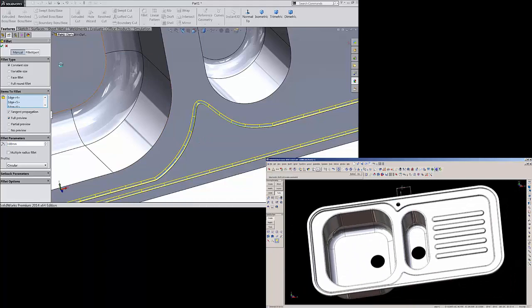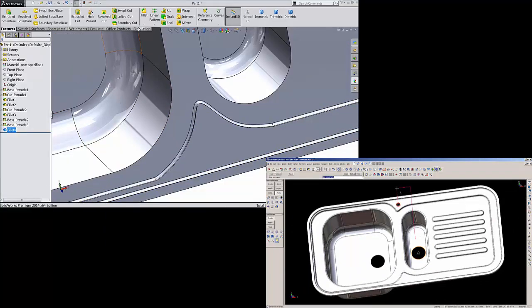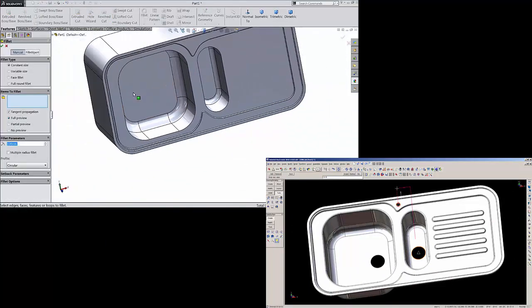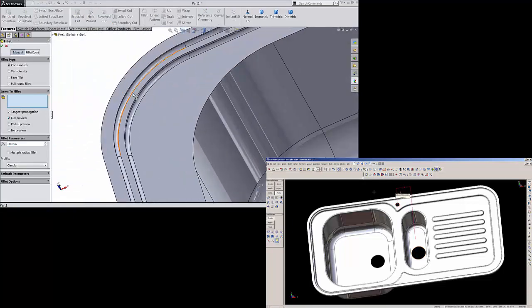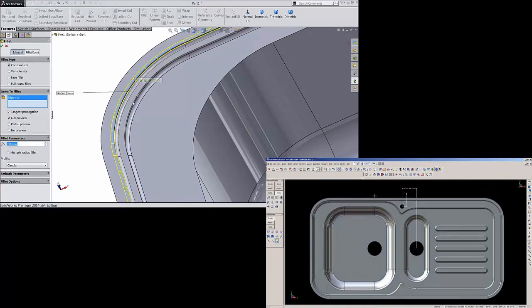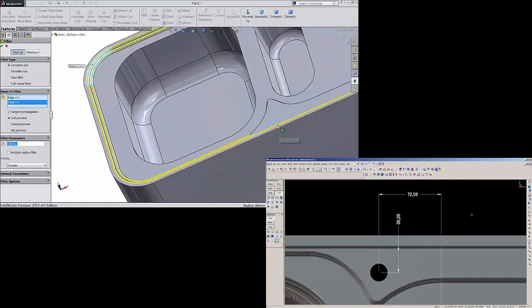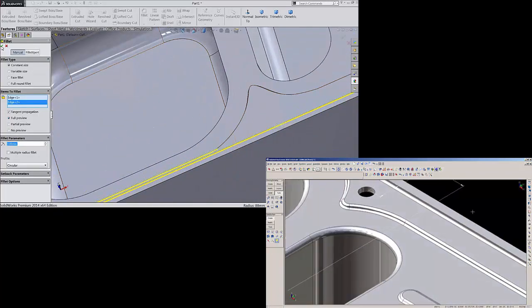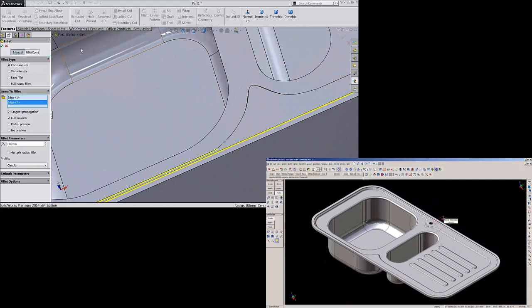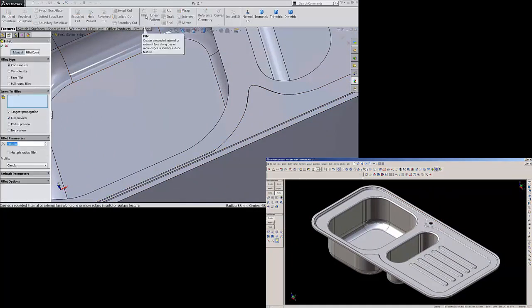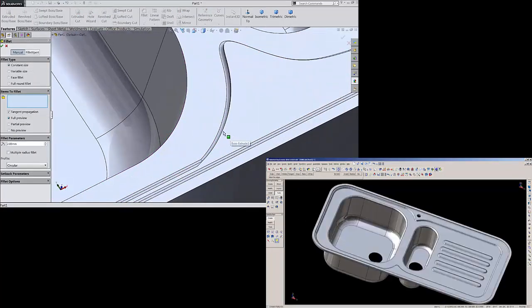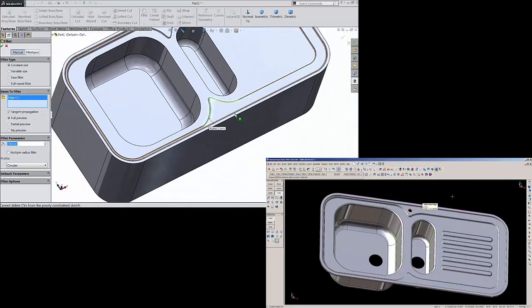Okay. Now again keep fillet, this time choose top surface and this also top surface, select OK. Fillet, keep 2 mm, and here select this face.